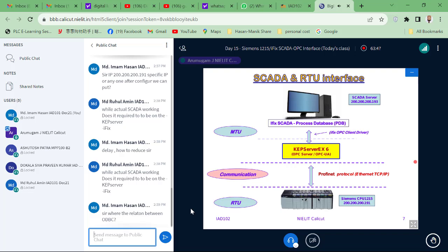Now in this SCADA, you see here what to do. In this case, this data, here an analog is there. For example, this is your analog value. This analog value, if you want, you can send to the OPC. How to send? You can send through the alarm concept. Enable this service, enable the data. This real data will be stored. Whenever an alarm is generated, automatically it goes to the OPC. That's all. You can send from here, or you can send the value from here also. From here also, you can send the data to the database.